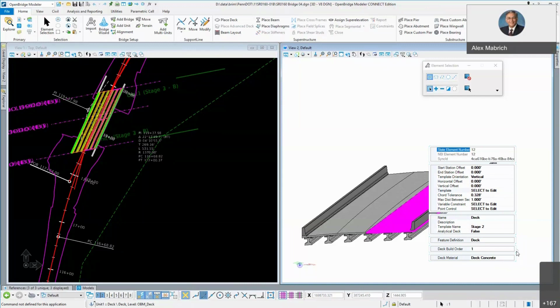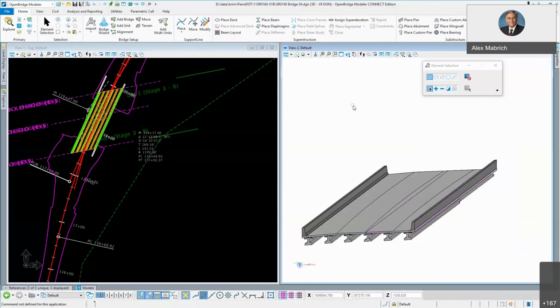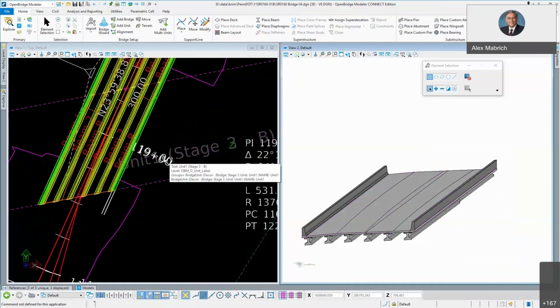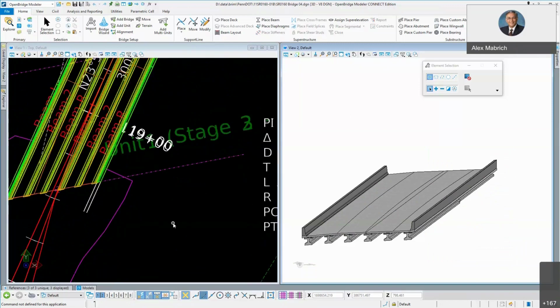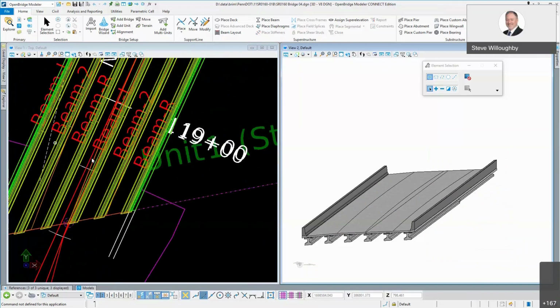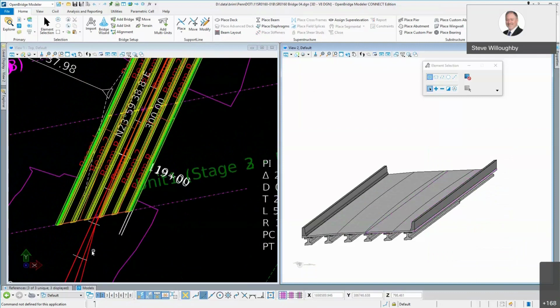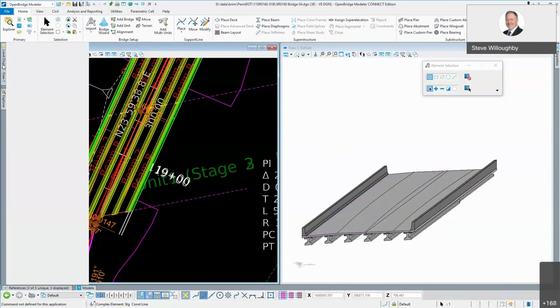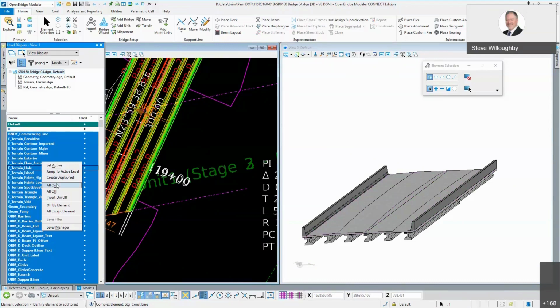Now the kind of workaround that Steve is proposing there is just, I mean, maybe prepare the bridge to have control lines, and then when you move the control line, the bridge will move too. So right, absolutely. Those white lines that I have out here for my alignment, like this line right here, I can change any of these values, and I really did it on purpose. I defined this one line, that one white line, off of, and here, let's just go ahead and turn everything else off.